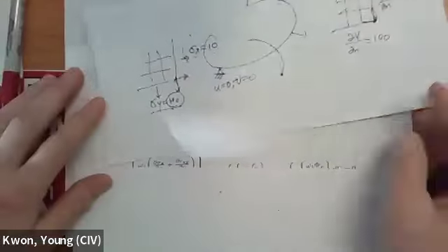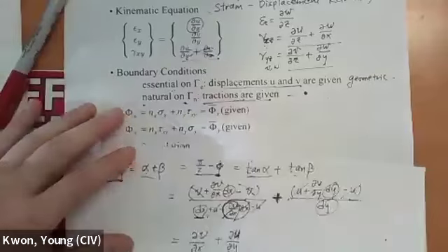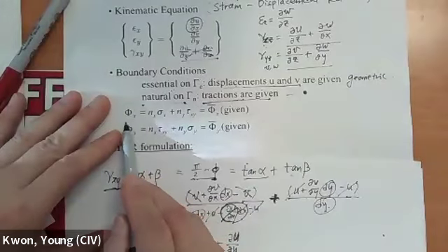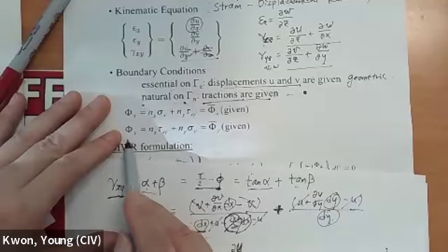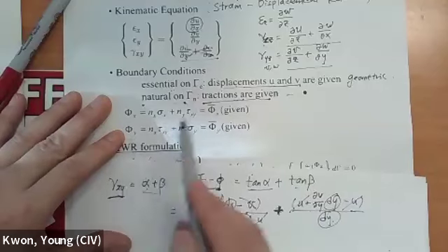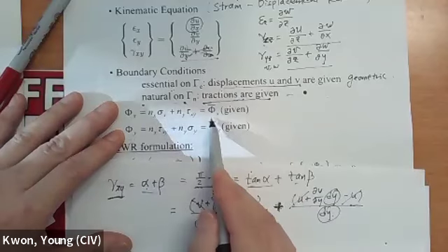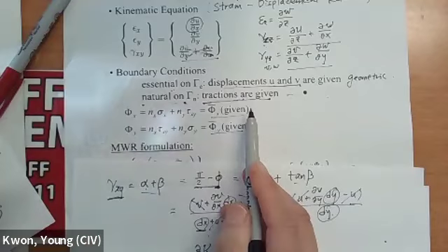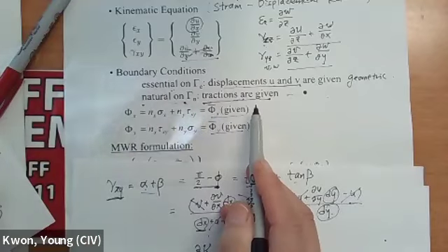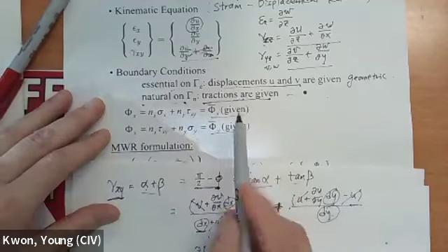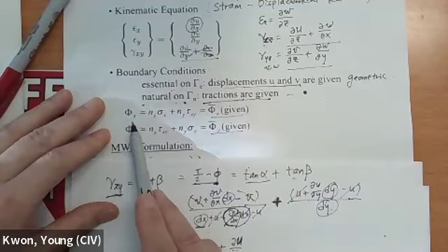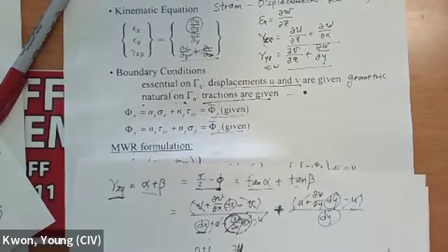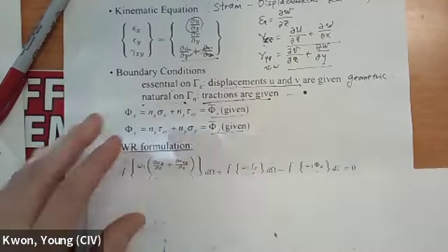So here you have traction in the X direction, for which we use capital Phi, and traction in the Y direction. Okay, so if that is given, then we have a known value. Unknown, we don't have to worry about it. The known value. Then what is the relation between traction and the stresses, sigma X, sigma Y, sigma Z? So that's what I'm going to show you here.